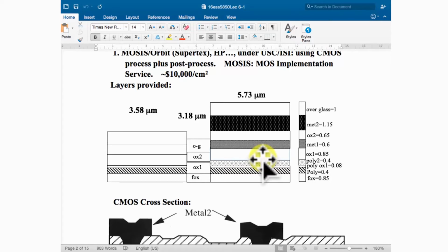You have 2 layers of metal electrodes, like aluminum, to connect the signal to the outside. One goes horizontally, the other goes in the other direction, so you can take all the signals out. The two metal process is an old process. Currently, TSMC provides more than 6 metal layers, even 8 layers, very thick, because they have a lot of connections in a small area.